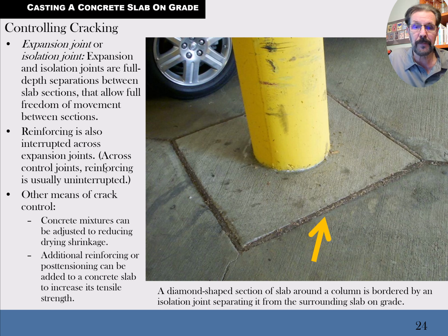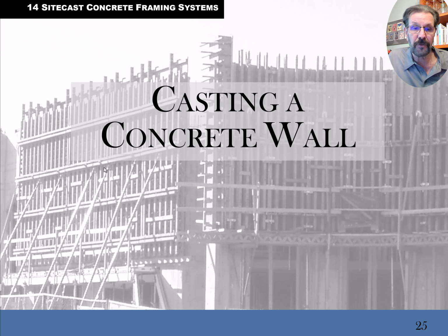And then the diamond box will typically have expansion joint material that it's made of so that it keeps the concrete from dragging this column from side to side. It's an important process. So you'll see lots and lots of diamonds out there around columns, light poles in parking lots and everything. Now that I've mentioned it, you'll start seeing them more often if you haven't noticed them before.